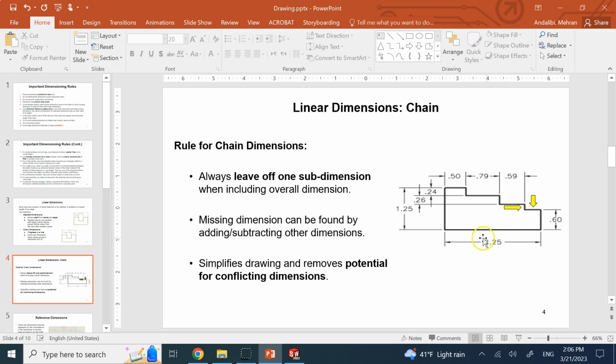Well, what would happen to the total length? Yes, because each one of them is made 0.01 bigger. Now this guy is going to be whatever I intended, the nominal dimension, plus 0.04 instead of 0.01. So you see, this guy will be out of the tolerance because I only allowed 0.01 for every dimension here. So all of those 0.01s are added together.